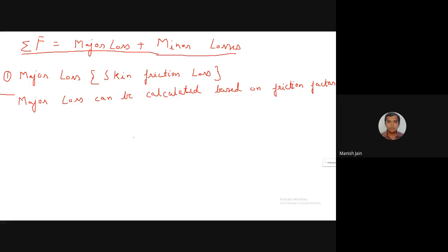And how the friction factor is defined, we had done this after the derivation of the pipe flow problem in the Newtonian fluid. Friction factor is defined as tau W divided by 1 by 2 rho V average square. The friction factor is a dimensionless number which provides an idea about the magnitude of the shear stress, that is, how much friction is calculated. Shear stress is nothing but the friction.